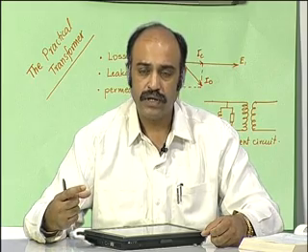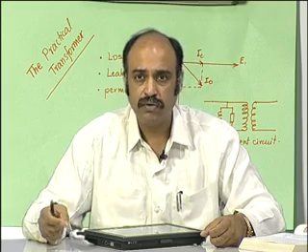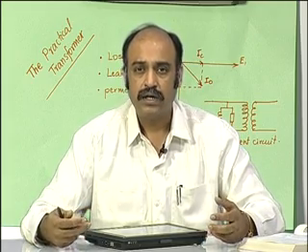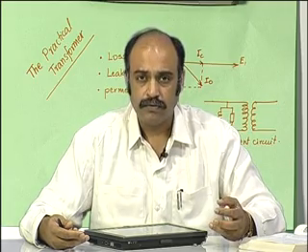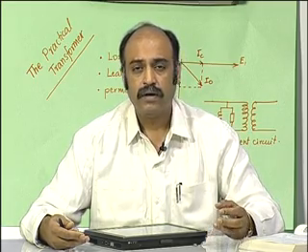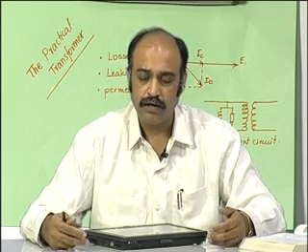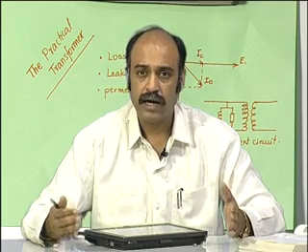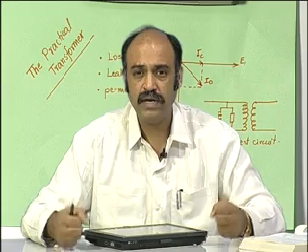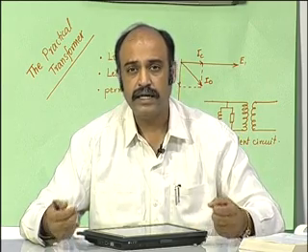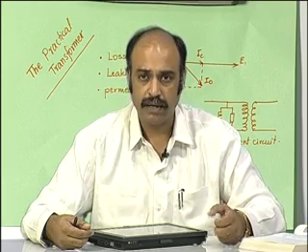So, if there is a completely reactive load, meaning if there is a reactive load of 1000 VAR and if there is a resistive load of 1000 watts, in both the cases the transformer has to be rated for 1000 VA, because that 1000 VA is what it has to handle, and the heating value of the transformer is actually related to the apparent power.